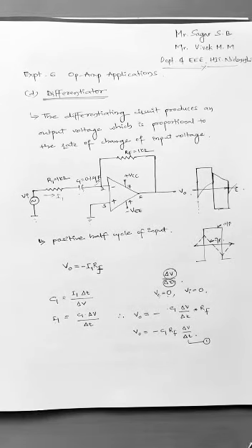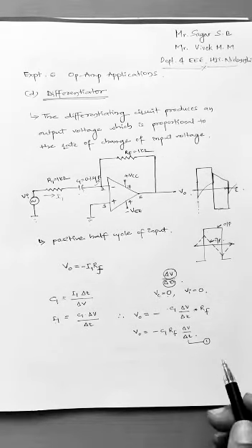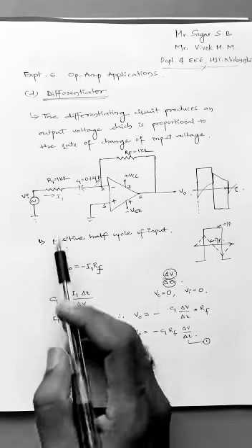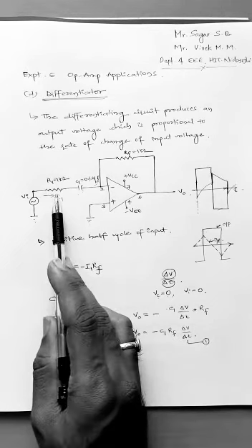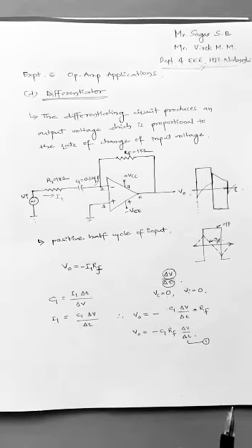You can note here the differentiator output of this circuit is inverted, that is the output voltage is a positive DC level when the input is negative going, and a negative voltage level when the input is positive going. One more significance of resistance R1 is that it is included here to prevent the circuit from high frequency oscillations. Now we will conduct this experiment.